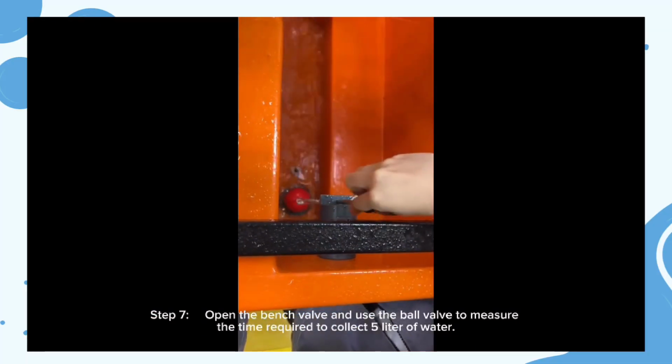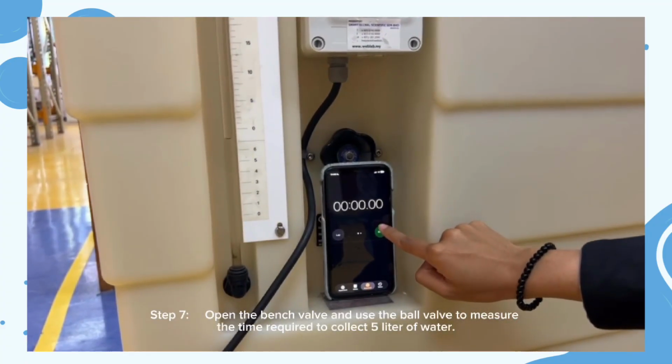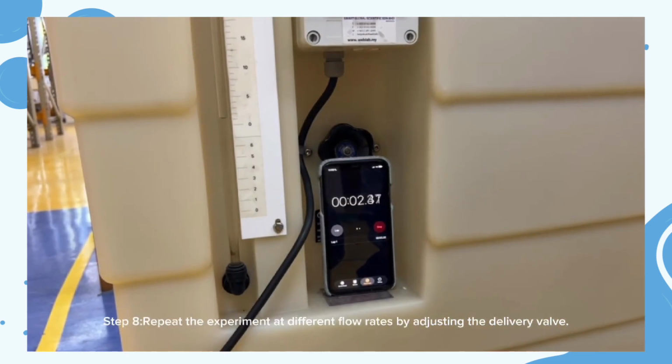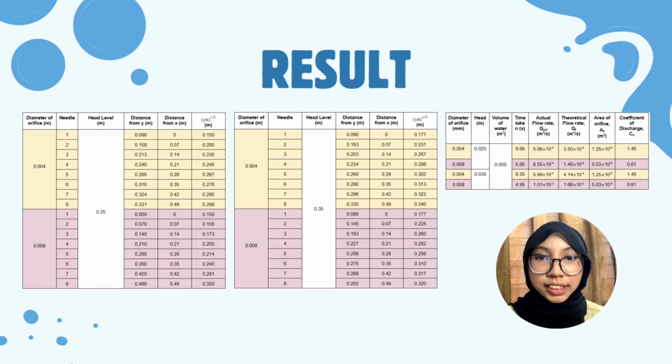And then open the batch valve and use the ball valve to measure the time required to collect 5 liters of water. Repeat the experiment at a different flow rate by adjusting the delivery valve. So this is the result that we get from the conducted experiment. We use two different manipulated variables, which are different diameters and different head levels.